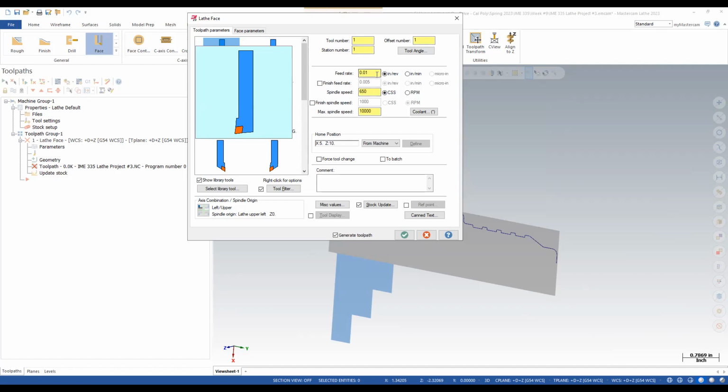So there's different ones. On the multiple spindle machines, you have 2 stations. Sometimes you have multiple turrets, 2 turrets actually. The post is the post processor that, when it creates the G and M code, doesn't grab every little piece of data out of here, only the stuff it needs for the specific functions it does on the machine, or the parameters that it has on that machine.